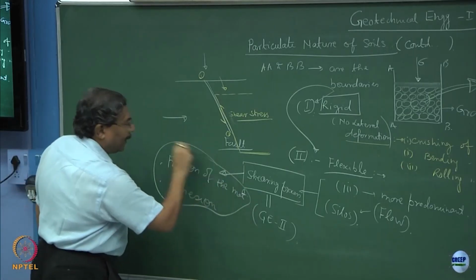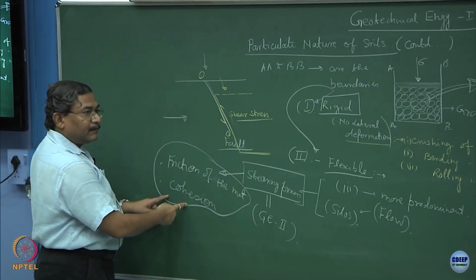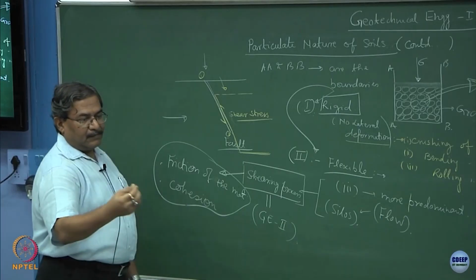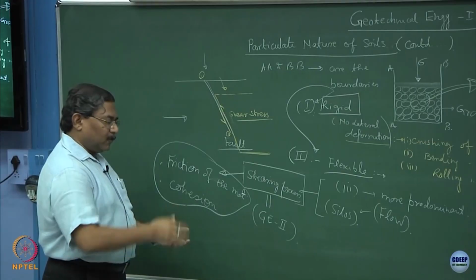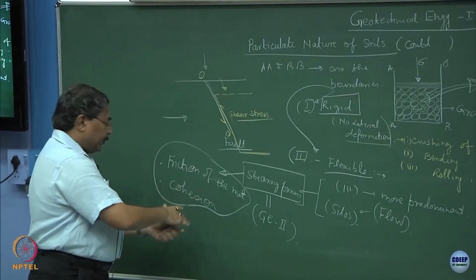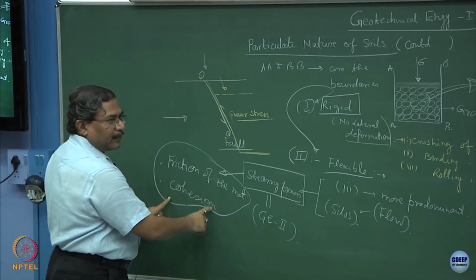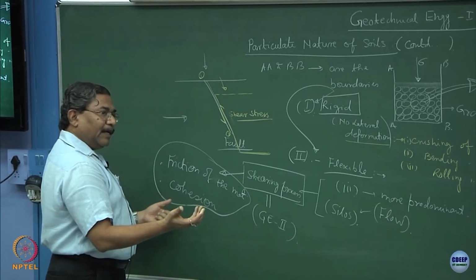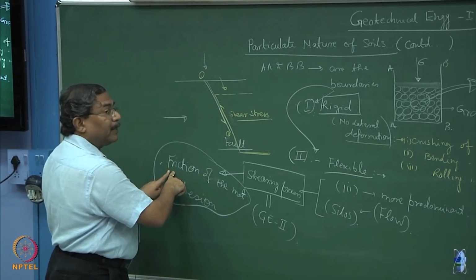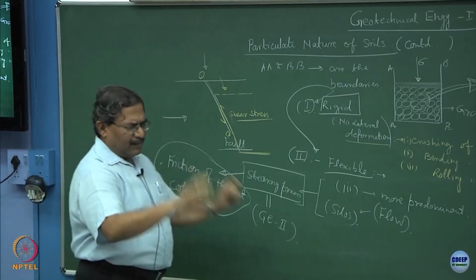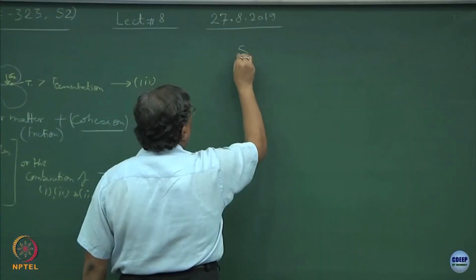Material would behave either in a cohesive manner, uniform material like clays, they are mostly cohesive. So, you press them, the shear strength is because of the cohesion. Granular material, sands, alright, you press them, the shear strength is predominantly because of the friction. Do not bother, we will discuss this later, clear.